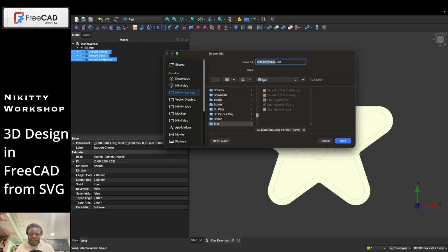Now we're already in the folder star. I'm going to keep it star keychain. If you want to keep what we just had, it had the colors in there, a little bit of that property. You want to save it as a 3MF if you want to keep those colors consistent when you pull it into the slicer.